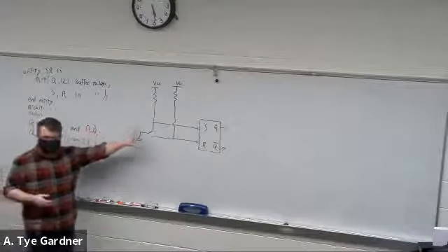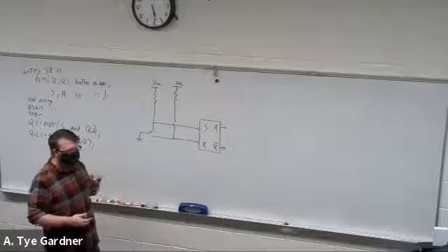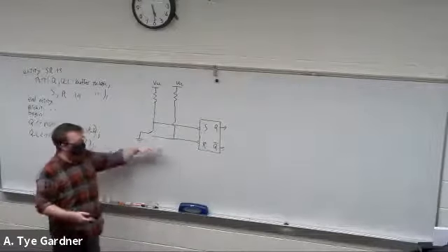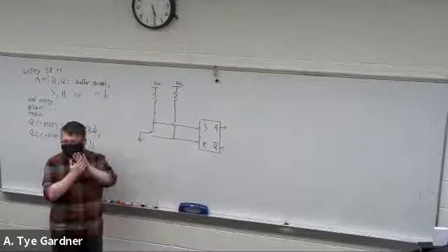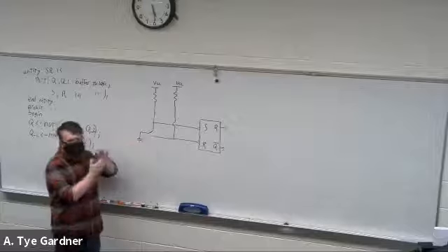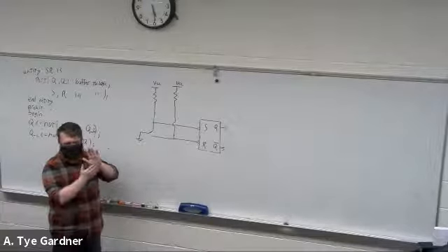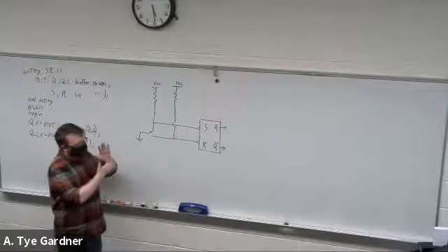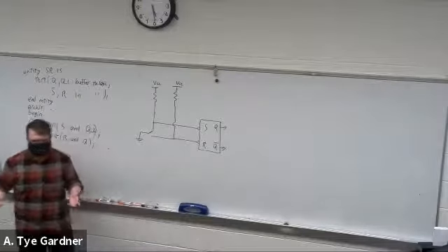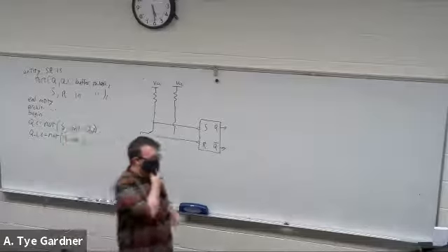This is a debouncing circuit. Same thing. If I threw it back up and it hits set, it was 0. It hits set that first time, sets it to 1, bounces off. It's not going to bounce all the way back down to the other way. It's just bouncing up a little bit. So it goes 1, 1, 1, 1, 1, 1, 1. Not an issue. Again, this is debouncing.